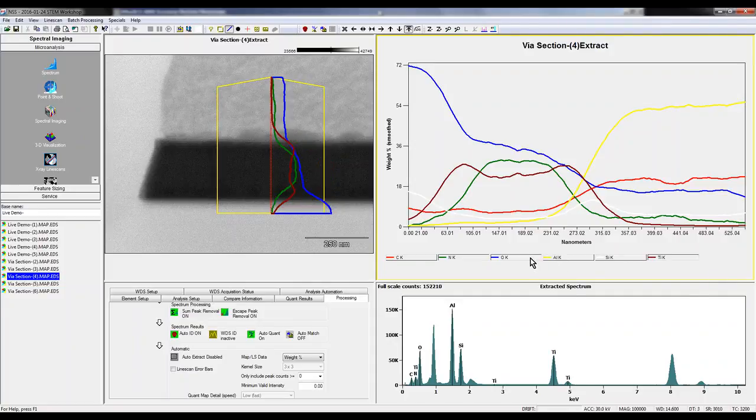And so if we look at the oxygen plot, we can see that there's a very, very high concentration of oxygen at this bottom edge, which means that some of this titanium must have reacted with oxygen in addition to nitrogen to form a mixed oxynitride as opposed to just a pure nitride. But then you see the oxygen drops off at the top edge, so it's predominantly the bottom edge where you have that Ti oxynitride. TiN through the middle,